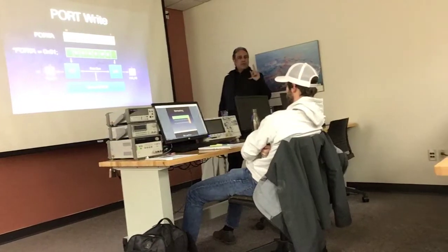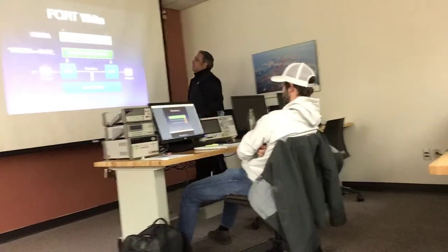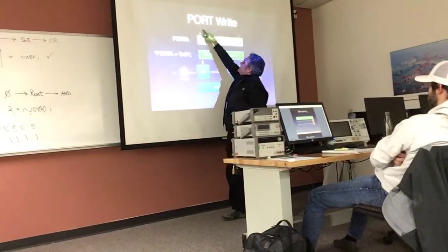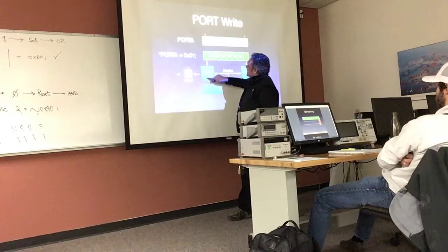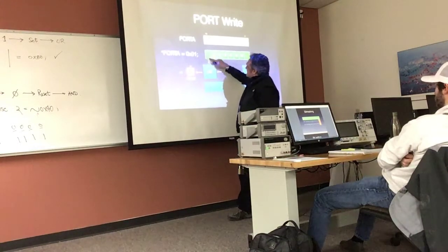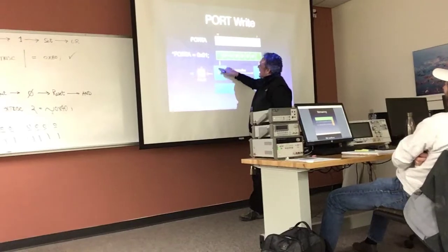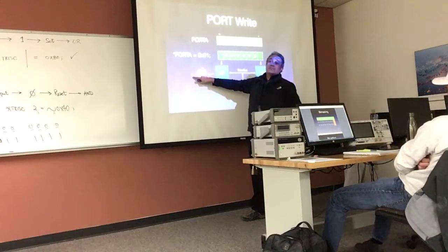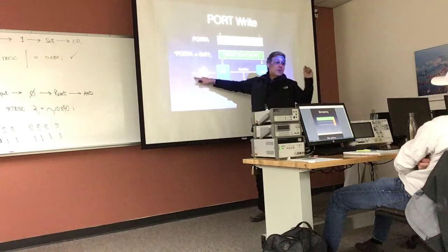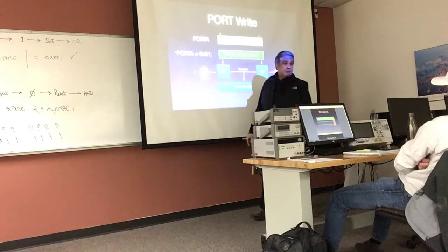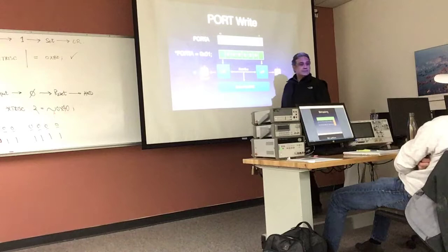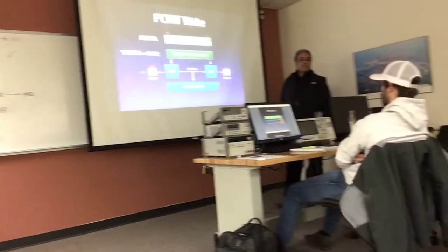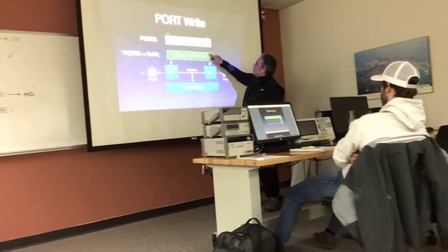What the system is doing is that when you write a 0 into the latch, the port sends the 0 to the latch, and the latch sends the 0 through the pin, and you actually experience 0 volts in the outside world for the first time. You can actually take a multimeter and look at it.